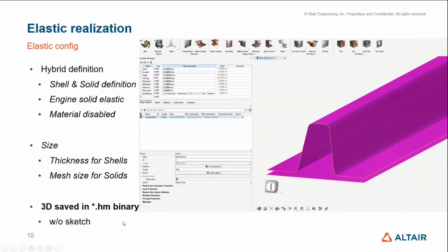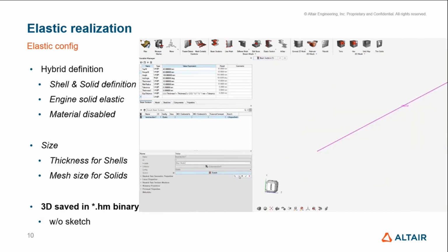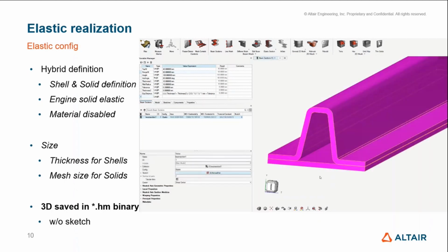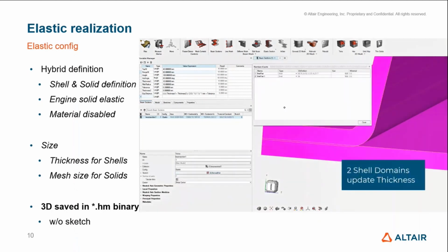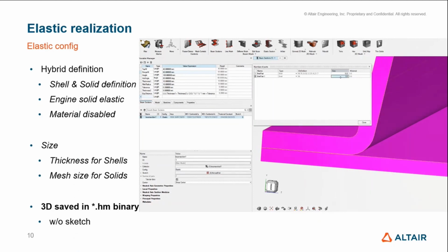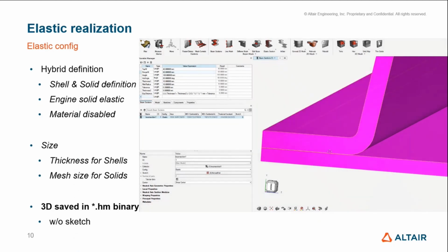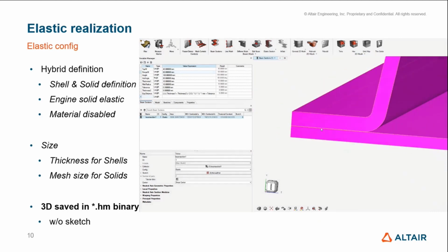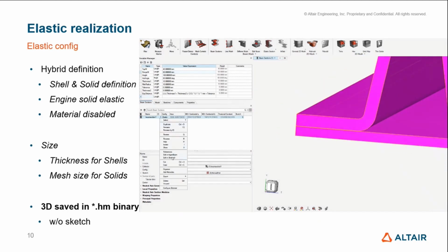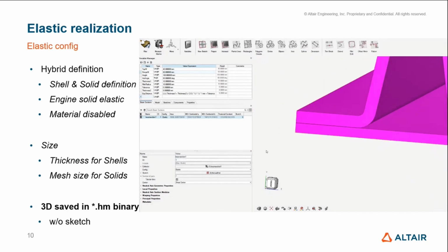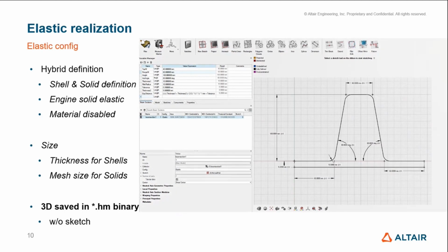So for demonstration here, I have one beam section of type shell pointing to a sketch. Since this one is used to a property, I just reset it to become an elastic section. I assign the same sketch and it recognized everything as a shell, but since the thickness was not correct, just by updating the tabular data, we can now have the part with a small gap. Yet since it's elastic section, it calculates the torsion constant by contact.